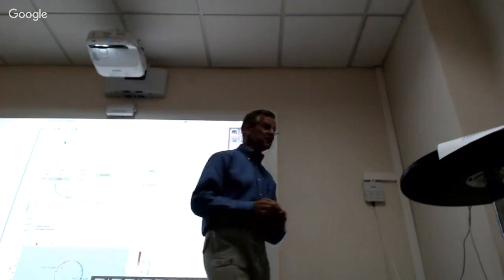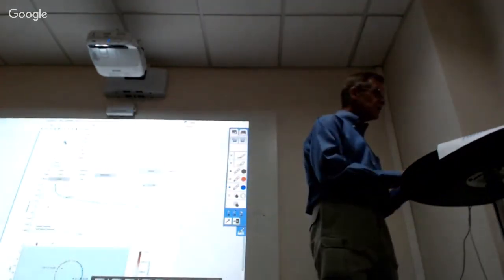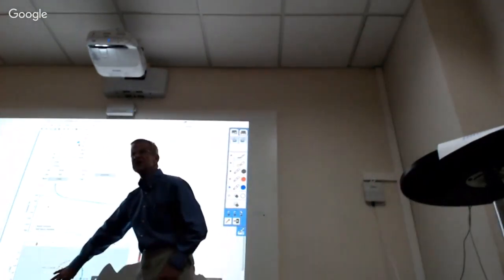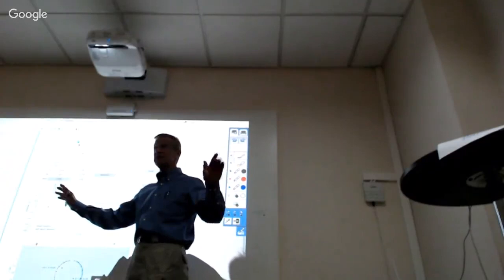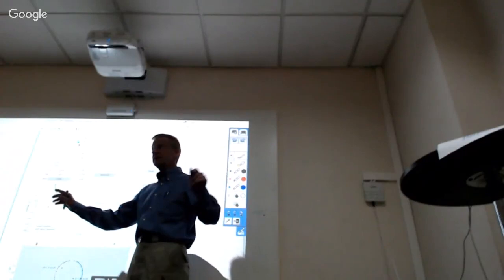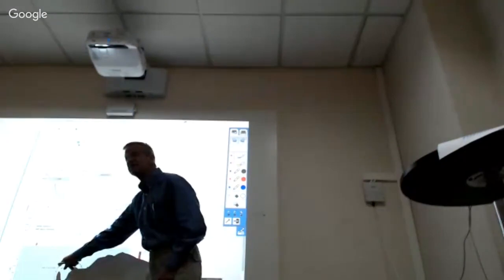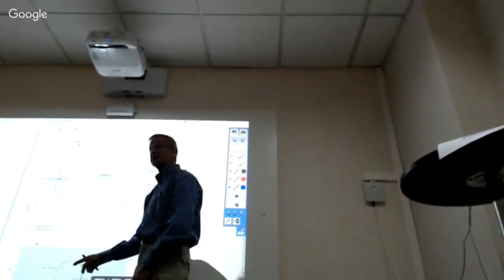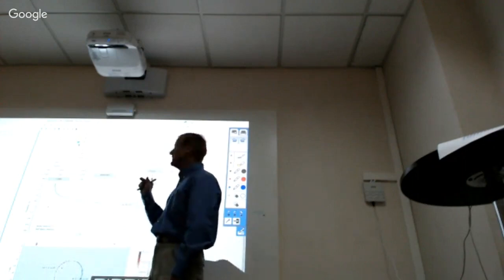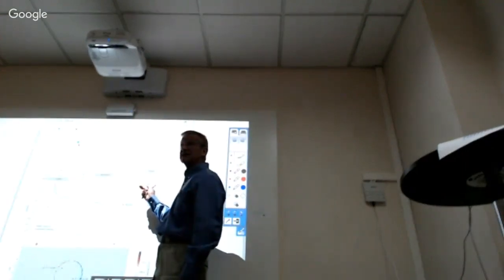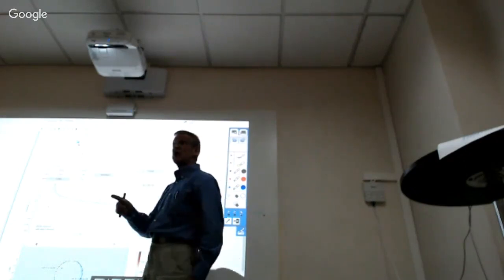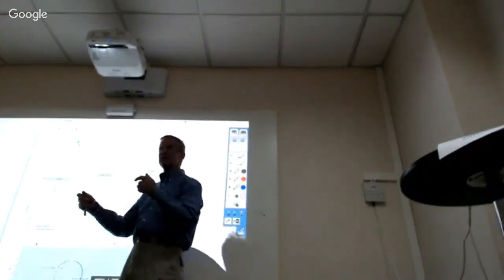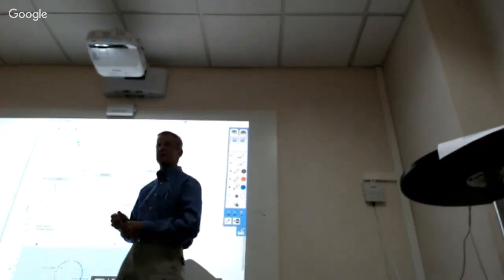That means the apparent resistivity has increased. Okay, now watch what happens if I go over here. So now I'm sitting over here. The charges haven't changed, right? I'm just measuring differently. I'm actually closer to these negative charges. Even though those are a little bit weaker than these guys, I'm actually closer to them. So that's causing my potential to decrease. Hence, I'm getting an apparent resistivity that's actually less than 1,000. So it's all in that whole combination of two things. One is exciting the body, and then the other is measuring. Like, where do you measure?